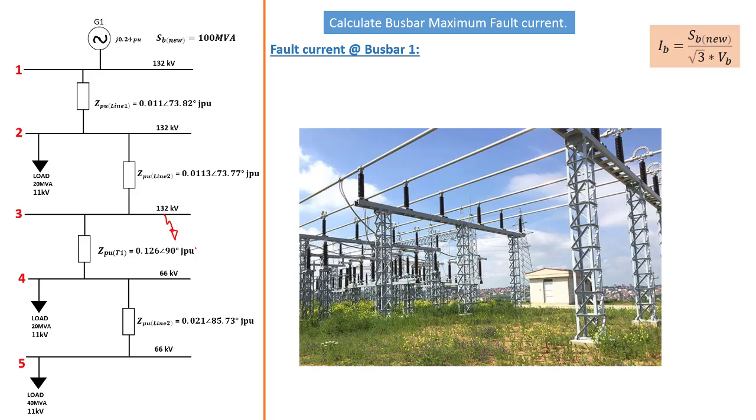So the purpose of this tutorial is precisely to determine the magnitude of the fault current on each one of these bus bars. That way, the design engineer that is designing the network will know exactly what kind of equipment and rating to place to protect this bus bar and the equipment that it will be supplying in case of a short circuit. Because if the short circuit occurs because of someone accidentally touching the live part, you want to protect that person as quickly as possible. Or if it's faulty equipment, you want the equipment also to be protected to minimize the cost of repair.